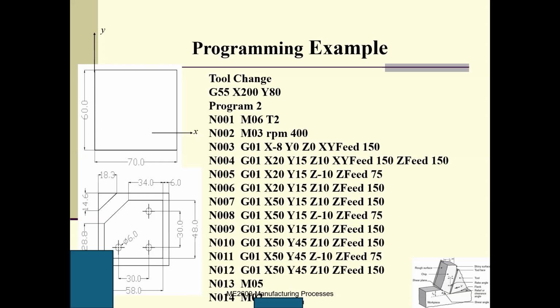So this is a 14, and this is 14, right? So this is the 14, and I also know this is a 58. So total length is 70, 70 minus 58 is 12. So that means this is a 6, and this is 6, right? So that means the 6 plus 14 equals 20. Right? So that's the reason I move to G0 x20 y.